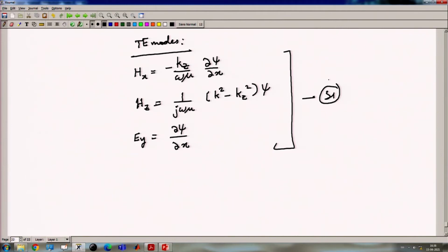Now, because the dielectric guide is an open structure, the concept of cutoff frequency for such guides is somewhat different compared to metallic guides, where the fields do not escape from inside the metal. So, what is happening here? We have the fields which are sinusoidally or co-sinusoidally dependent on the x coordinate inside the dielectric slab and which are exponentially decaying above and below the dielectric slab.